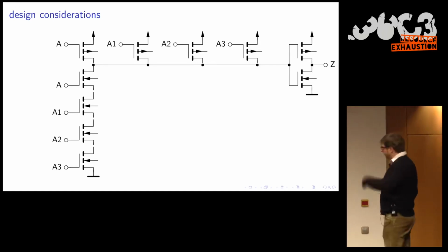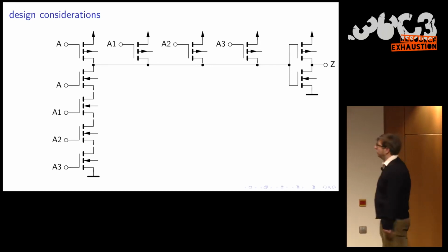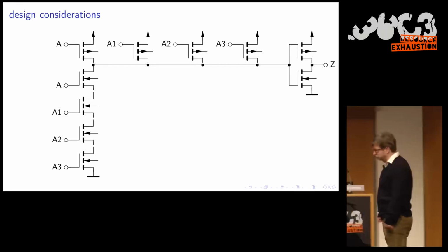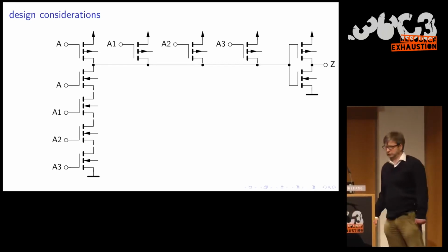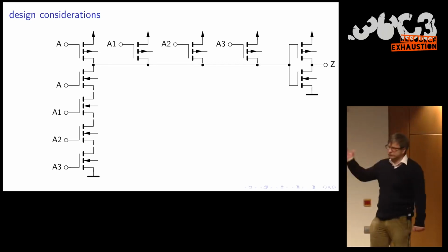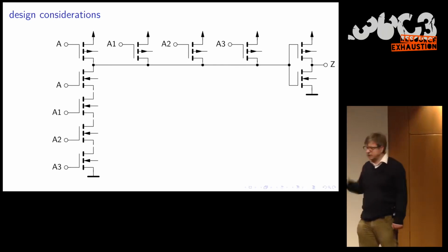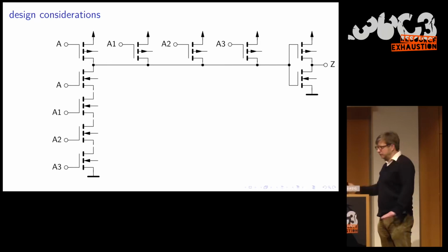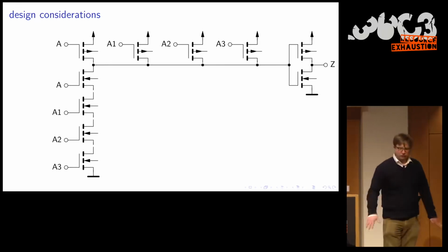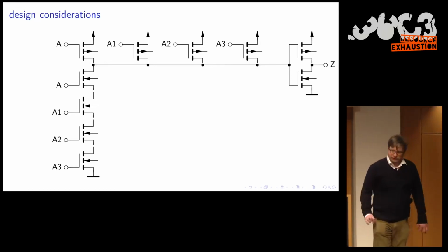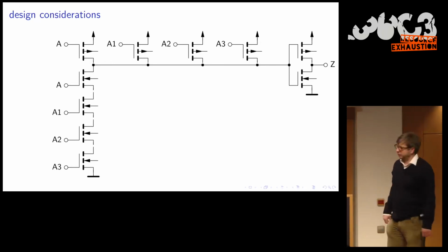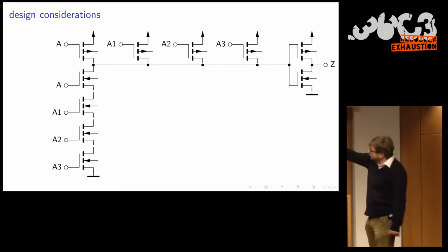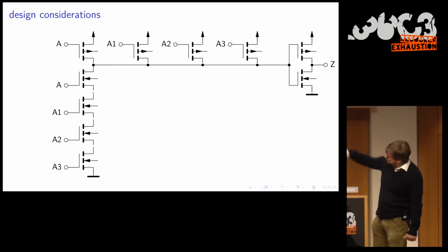How much do I have to buffer at the end? So I have maximum 4 transistors here, but that's configurable in the tool. But I can think about places where I do 3 or 2. So 4 transistors is okay for 1 micron, but with smaller technologies we have a voltage problem.